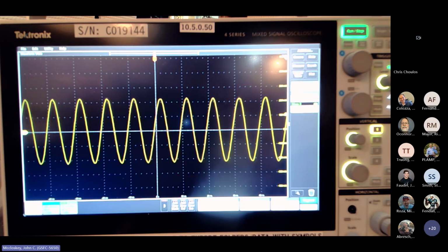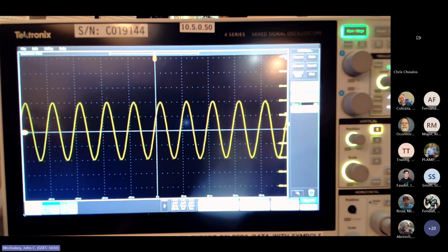This is 111 dB microvolts. That's actually 157. That's a little high. So, all right, let's split the difference and go to like 110.5. Okay, that's right around 150. Okay, so we'll go with that. So it's about half a dB higher than what I needed the other day.